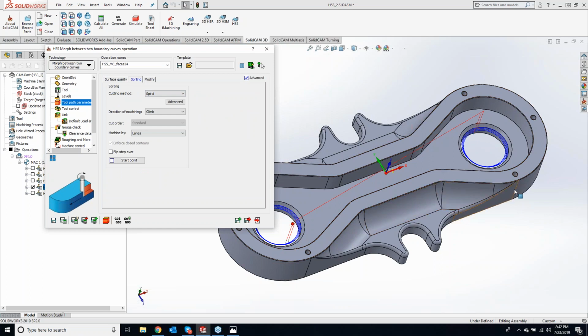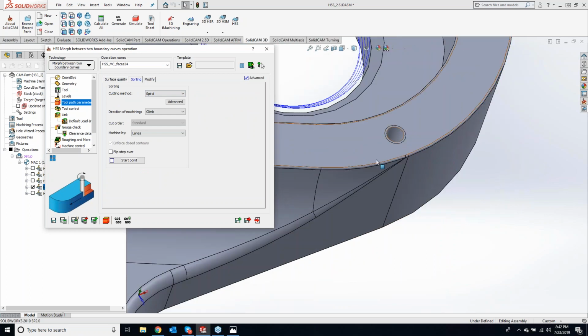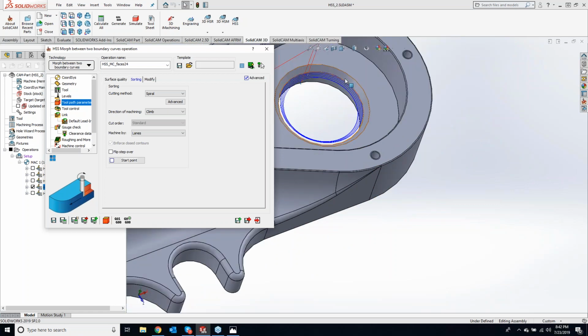And I would do a spiral for a lot of these radiuses that have a continuous radius going all the way around. So like we got this top radius, we got this inside radius, we have this chamfer right there. You get a really smooth finish, and that way you don't have any transition points, because it's constantly stepping over that amount using that spiral functionality. So that is a huge go-to.